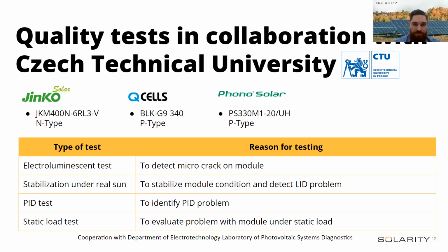So this is that electroluminescence process. This can detect hidden defects in the structure of PV cells, and why we do it. We can see micro cracks, cell cracks, PID, diode failure, or that the cell backsheet can also be scratched, and wafers can have defects. So then we continue with LID.